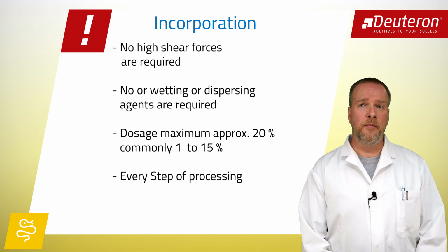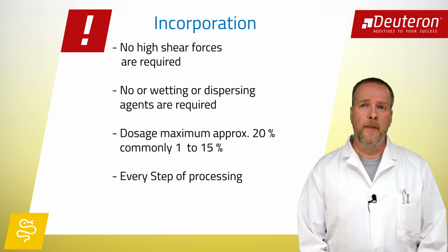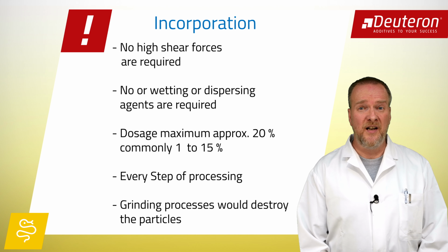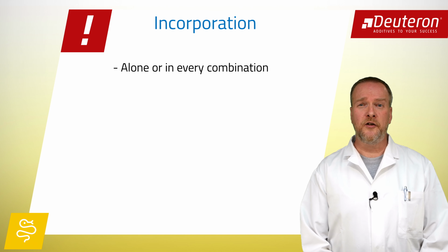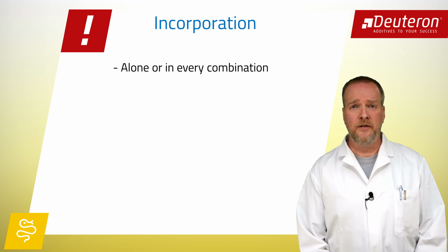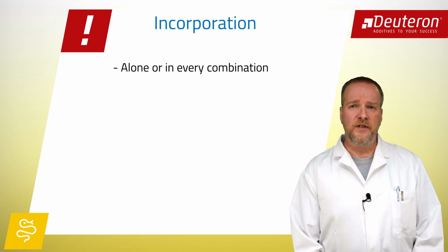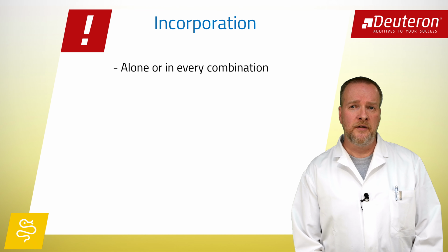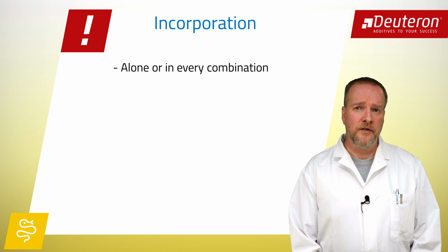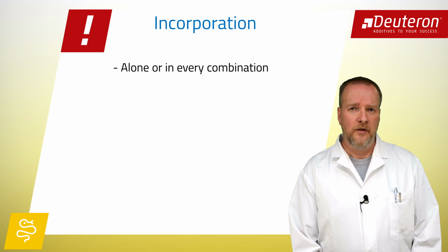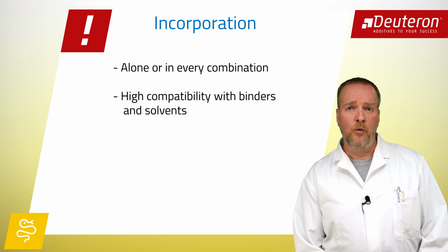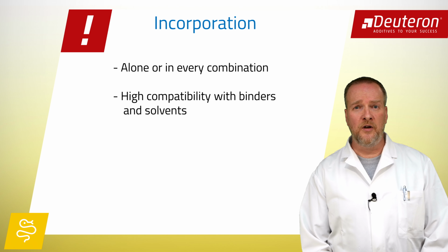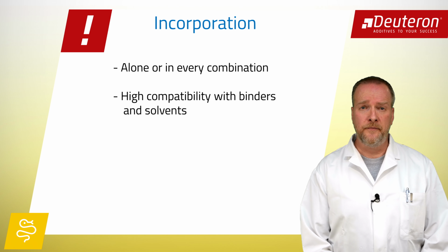These polymers are comparably hard and a bit brittle, but they are not indestructible. Thus, grinding processes in mills should be avoided. They are highly suitable as sole or additional texture agents in coatings. They can be combined with any other solid like pigments, fillers, matting agents or other texturing powders. There are no limitations. Limitations regarding compatibility with binders or solvents, typically for coatings, are not known to us.